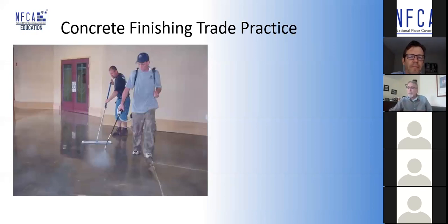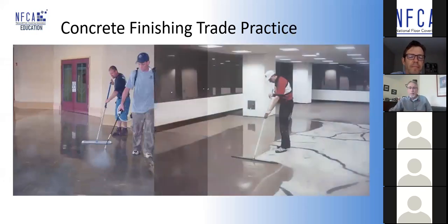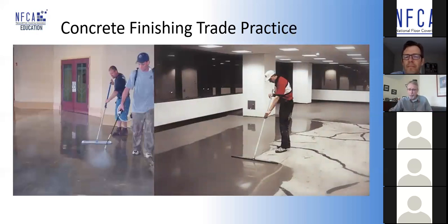Good. So here you can see this guy's working with wet materials. Even though it's called dry concrete finishing, we still deal with wet materials. You can see they've gone in and filled in the cracks with high viscosity crack sealers. These are non-moving cracks that always occur in concrete. This guy is spreading out the self-leveling underlayment.